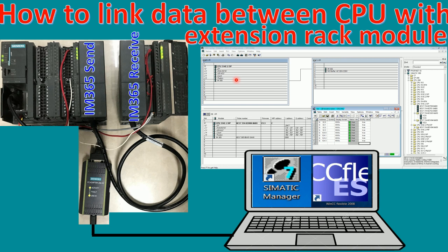So here is just an example, we have rack number 1 and rack number 2. Yes, number 1 and number 2. This one is linked by the IM365 module. Yes, and we can see here we can connect with it, and if we insert this module, this one will appear automatically. So if we have many I/O here and here, we can extend the module.